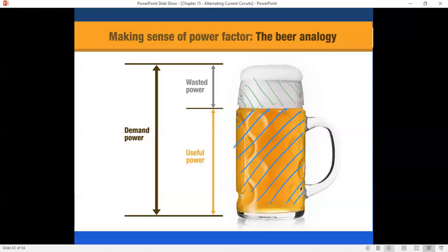So the challenge during high peak loads is that the users are not just using a lot of power, but these loads are large inductive loads. The largest users of power have these power factor correction units, but at home, you're just plugging your air conditioner in. You don't have anything fancy like that to improve this.